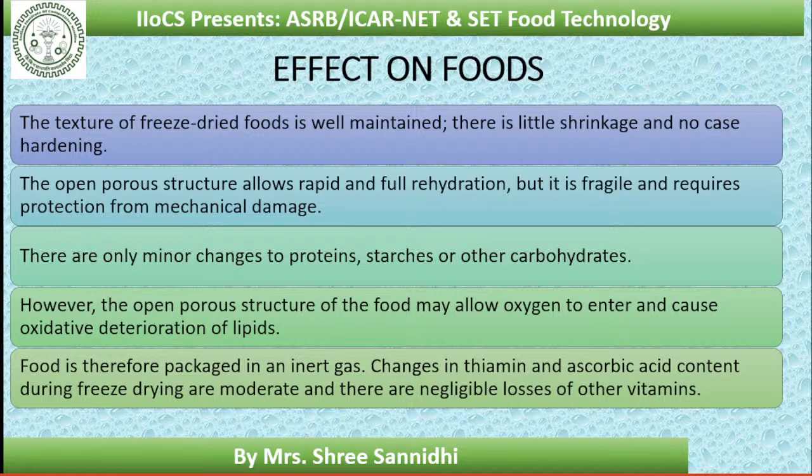Let us see the effect of freeze drying on foods. The texture of freeze dried foods is well maintained. There is little shrinkage and no case hardening, unlike the conventional drying methods. The open porous structure allows rapid and full rehydration, but it is fragile and requires protection from mechanical damage.